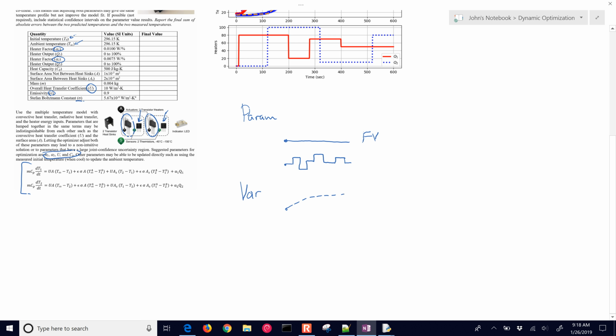Okay, something like this. And I'll go ahead and write MV here. If we have a state variable, looks like my pen is having a little bit of problem today. Okay, or a controlled variable, but it does give a cool dashed line there. I kind of like that. Okay, a controlled variable is going to be something where you might have a set point range, and it's going to try to keep it within the set point range. Okay, so that's going to be a CV.